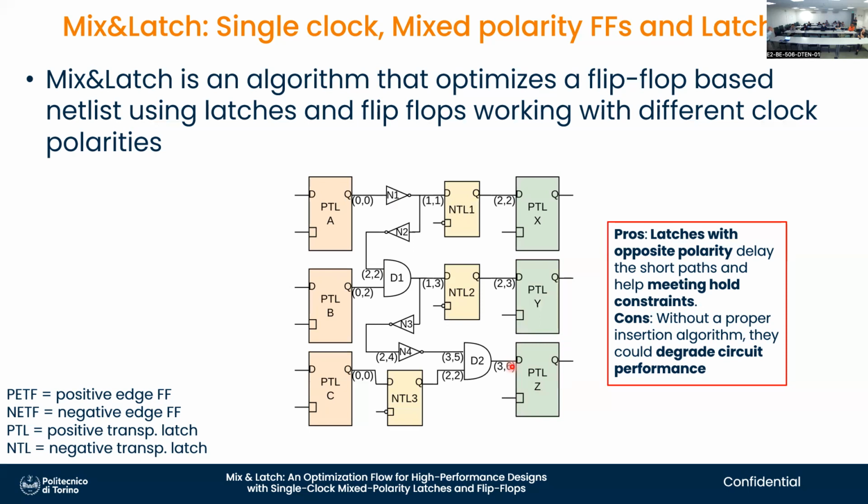There's always some edge on every short path. There is some edge, some gate to gate or gate to flop edge, which can be slowed down. And if you take enough of them, you will eventually be able to slow it down enough to meet the whole time constraints. Now, here, the result I'm quoting is not exactly the same thing as what we're doing here, because here we are not doing continuous slowing down.